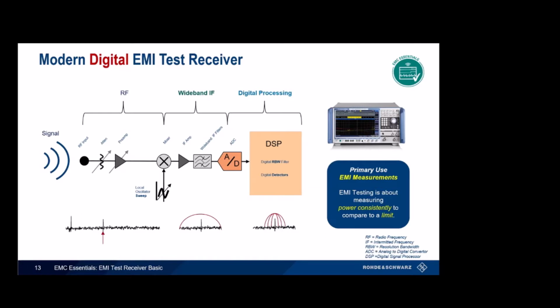We can limit the possibility of this RF overload by limiting the RF spectrum. To do this, we can add a bank of selectable filters called a preselector just in front of the mixer. This will reduce the RF power into the mixer.